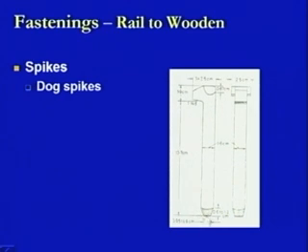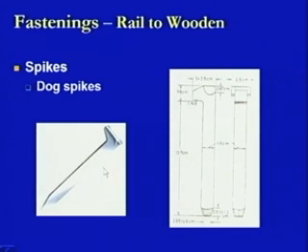It has this conical surface at the bottom through which it will be inserted into the wooden surface. So, it is hammered from the top and then it goes in, because of this conical surface, initially it will take a penetration condition and then through that penetration it will go inside the wooden sleeper. So, this is how the dog spikes work, and this is another view of the dog spike, where we have a little more conical surface in this one, whereas in this one it is a truncated conical surface, so that it is a little blunt at the bottom.